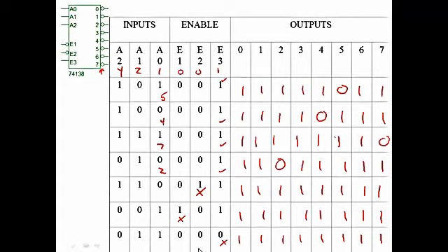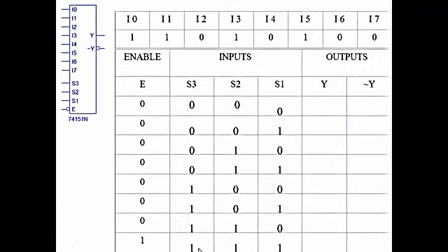So let's go on to the next one. This is what's called a multiplexer. And what a multiplexer does is it ties multiple inputs to one single output. So it's a way for us to tie all 8 of these inputs over to a single output. And the Y naught is just the inverse of Y. So we can do 0 through 7. We've got different inputs here, and you can see on my chart up here, I've just given you a random set of highs and lows.